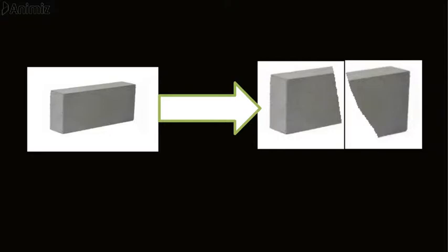That is a fine-grained soil. But for our convenience, we are cutting into two pieces. When we try to join the two pieces of block, they can never fill the space and act like one. Voids are surely going to be in between. So we can say that for the increased surface area, the void ratio in the fine-grained soil is more.